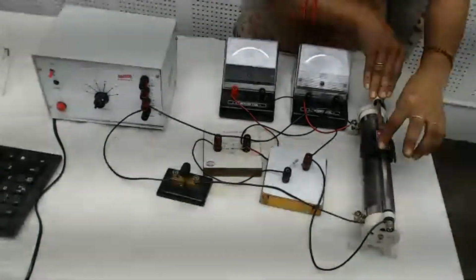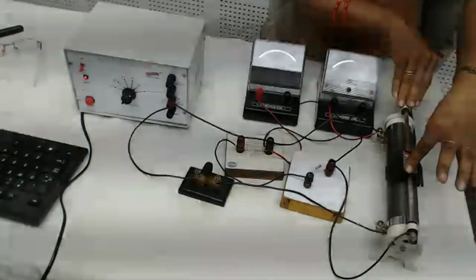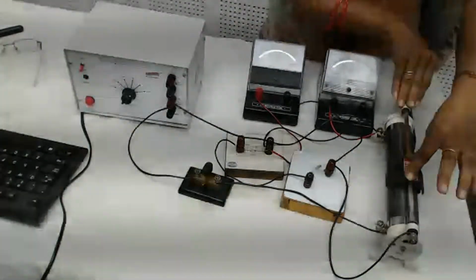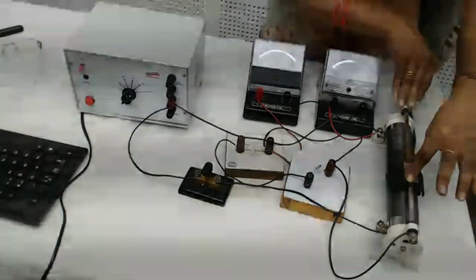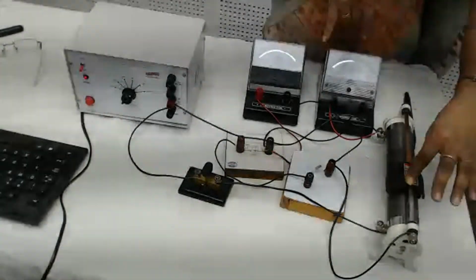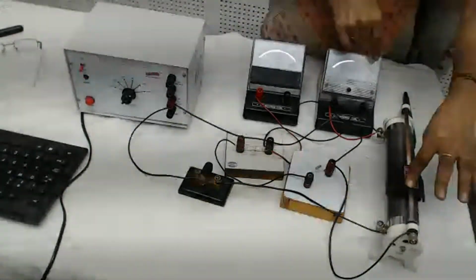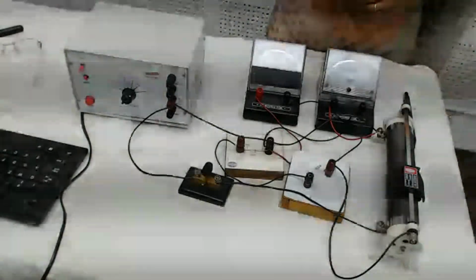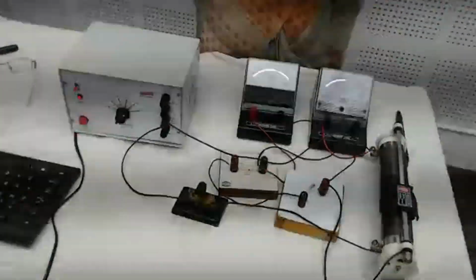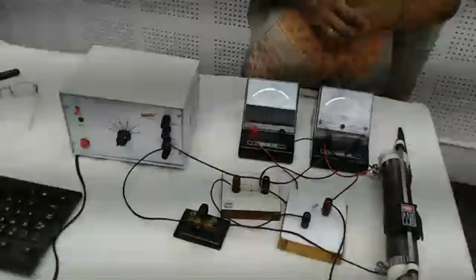As voltage increases linearly, there is a linear increase in the current also, but beyond the breakdown voltage, at one particular voltage of the diode, the diode breaks down. If you observe here, I will show once again, a sudden increase in the current takes place. In this way, the Zener breaks down at one particular voltage where a sudden increase in the current takes place. That voltage is called the breakdown voltage.